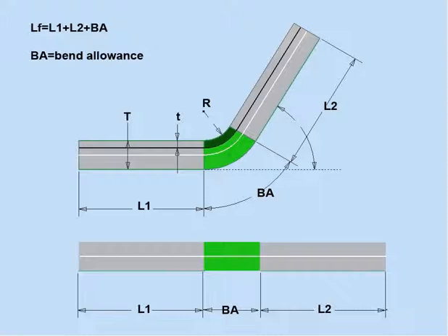There isn't exactly a scientific method for predicting the exact bend allowance due to the many variables at play in the bending situation. For example, actual material thickness, tooling conditions, forming methods, and so on. There are so many variables. In reality, many different methods are used. Different methods will work for different situations and different engineers. As you can imagine, trial and error is a very popular method.